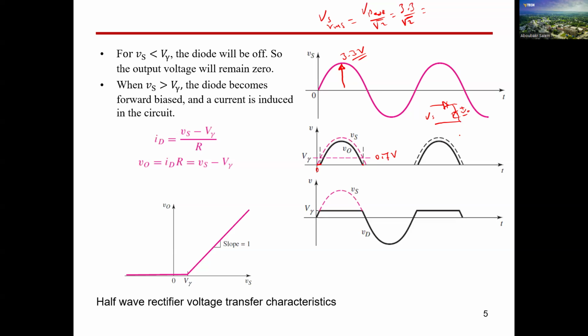Since this is a resistive load, and you know, guys, for any resistive load, the voltage and current are in phase all of the time. So if we have a resistive load, this is a phasor diagram. If this is V, I should be in phase. This means this is for R load. So the voltage and the current should start and end at the same point, which means the current will be 0 at this point also.